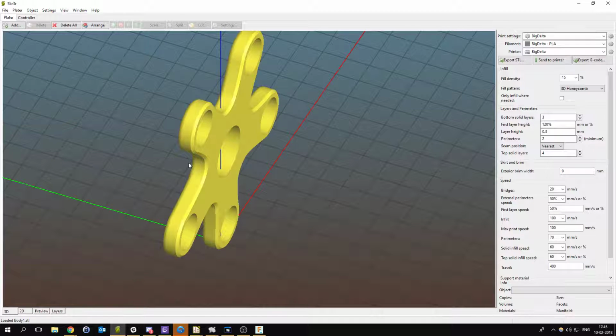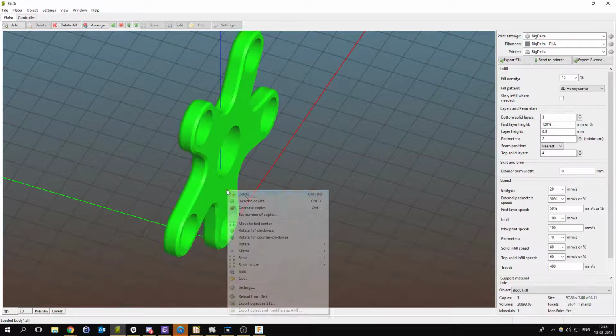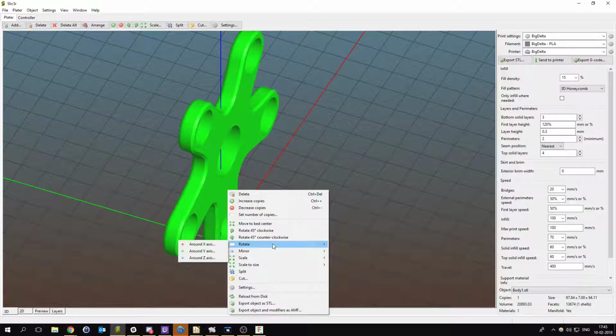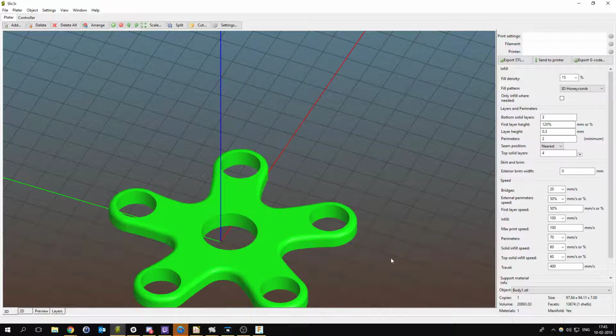What I can see from this is that in Fusion 360, y is up. So if you want to model it in your software so that it lays flat when you pull it into your slicer, make sure that the z-axis is what you consider up. There might be a setting you can change, or you might just put it on the front plane instead of the top plane. But you can also just completely ignore that and just rotate this around x 90 degrees.